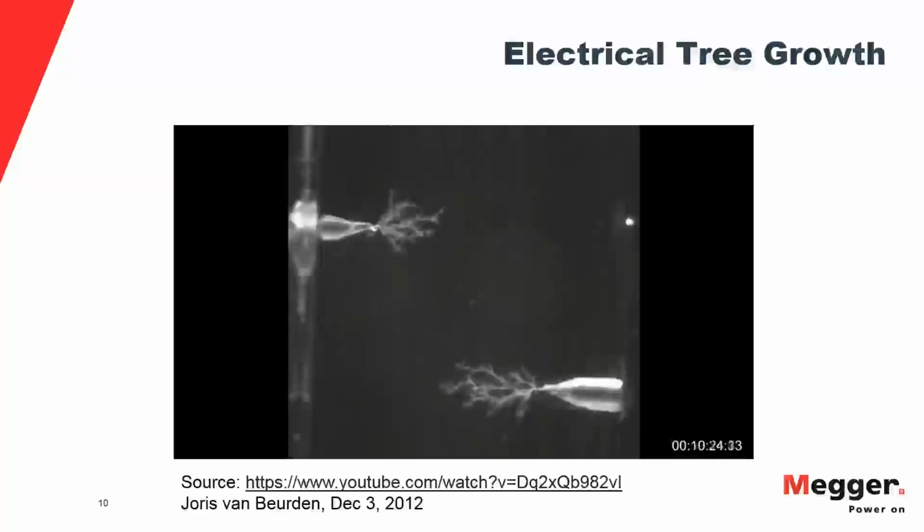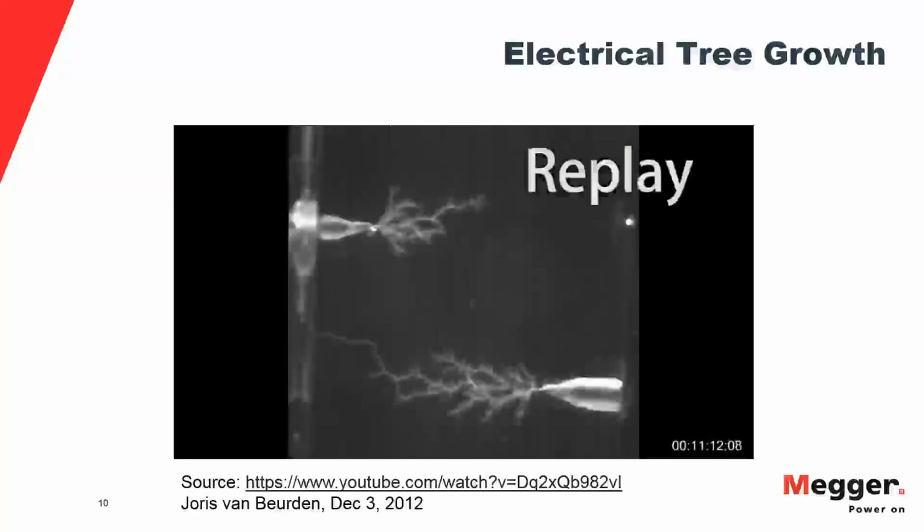If this video would play, there we go. So what we'll see is on the bottom, you have minutes, seconds, and frames. So we're already up to about 2 minutes of electrical tree growth. This does take a little bit for the trees to grow. And in this video, it's the bottom one that fails. So keep your eye on that. And what you'll see is that the trees start growing and growing. And at some point, the bottom one especially will just kind of accelerate to a very quick failure. So it's starting to accelerate now and fails very quickly after that point.